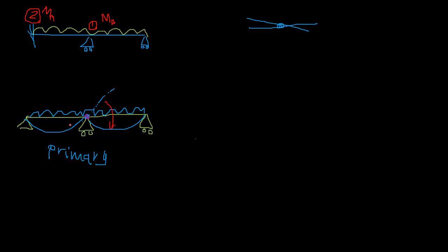right? So if it is theta, because these are symmetric, this is also theta, this is also theta. So the total relative rotation is going to be 2 theta, right? Compared to this part has moved 2 theta, right? So this part, originally it was here, it is now theta. So this relative rotation is also applicable for internal support, right? At the end, you can take the same deformation.